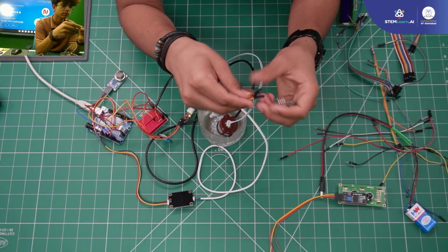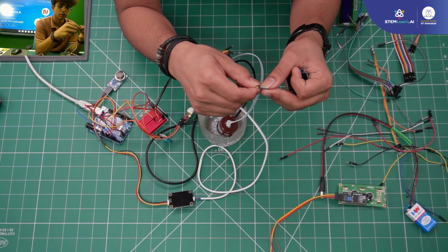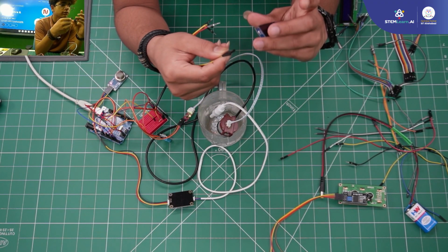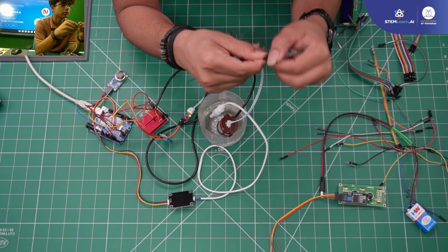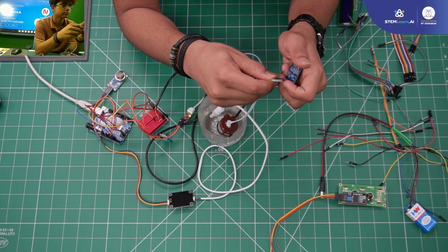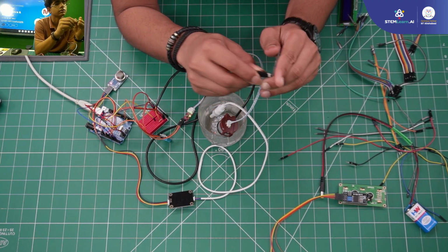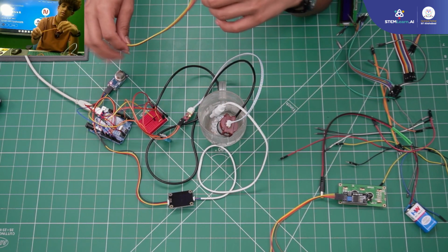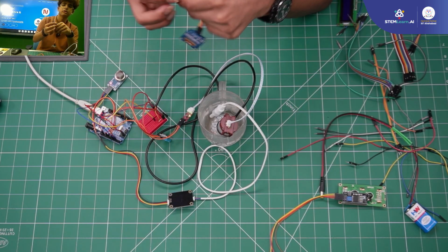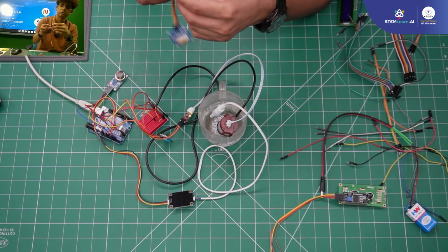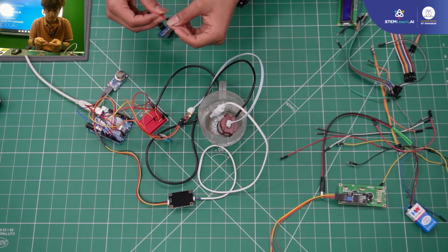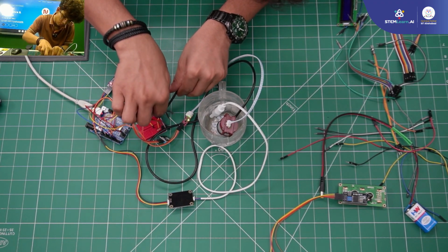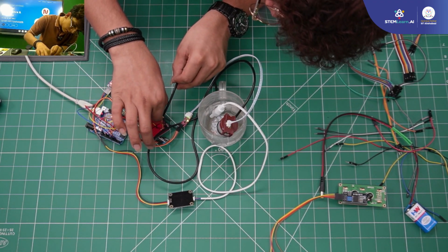I'll just get this pin here and connected. VCC and ground are beside each other. It's a good thing, we can just directly connect them side by side just like this. This is also I2C, it has its own address, but because of the library that we are using, we don't need to care much about it. We'll go here, connect it on the breadboard where everyone is connected.